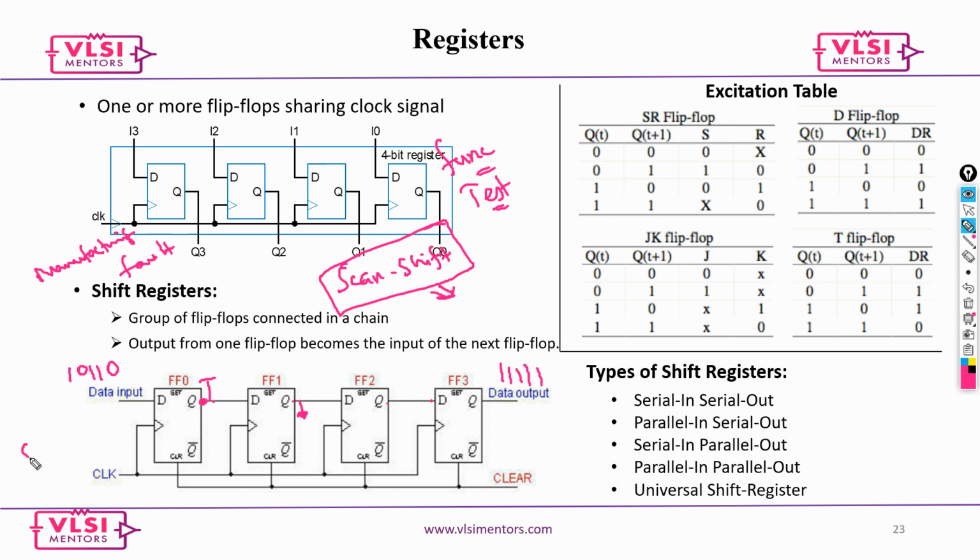That is something people call stuck at zero or stuck at one. So it could be one of these. In this case, it is likely stuck at one. So you need to test it. That's basically, this chip is dead. But now, where is the problem? Is it a one-time problem or are all the chips having a problem? These are all the works that during testing they will figure out, and then the foundry guys will look at it, correct it, and try to improve the yield. So the shift registers are very much used to test whether all the nodes are free from stuck-at faults.